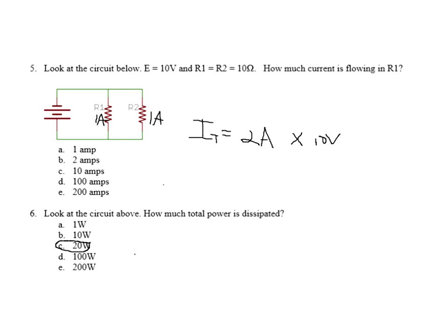Okay, how about if I took the reciprocal of both of these and added them together, the ohms, that would give me, and I think I would get 5 ohms for two 10 ohm resistors in parallel, and 5 ohms with 10 volts, 10 divided by 5 ohms gives me 2 amps. I could get it that way. Or I could use V squared divided by R. Okay, that would be a power formula. Or I could use I squared times R. So there's many ways to find power, but we try to stick with the easiest way.